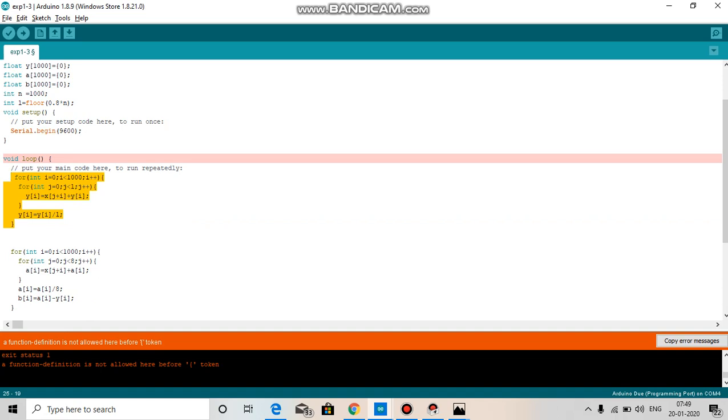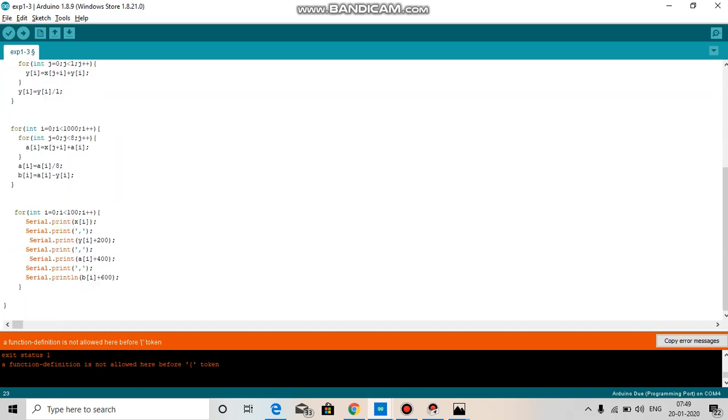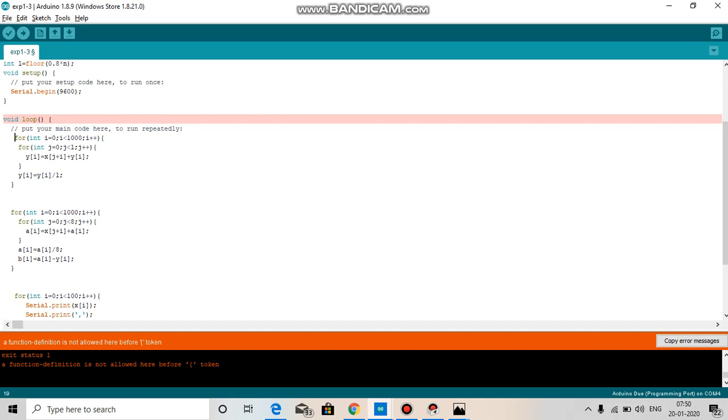A commonly used variation of this algorithm computes the average slope between adjacent points, which is called the central difference method. Its advantage is that it does not involve a shift in the x-axis position of the derivative. This is where we get y of j as our output, and this is for plotting the signal, and this is the main algorithm for the 3-point central difference derivative filter using the moving average filter.